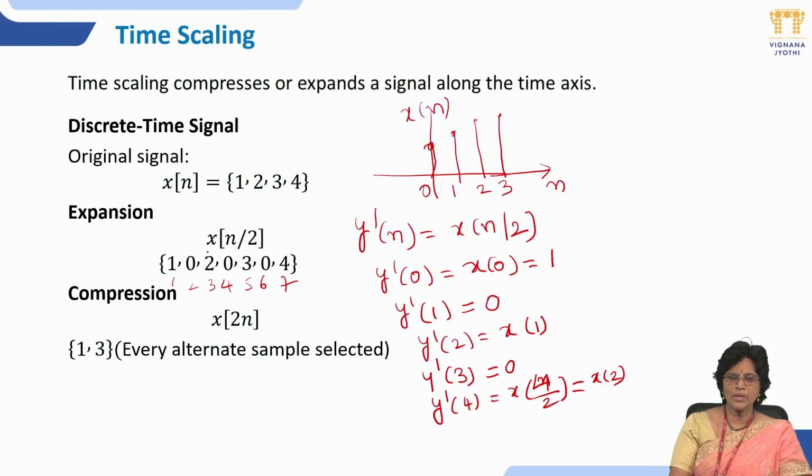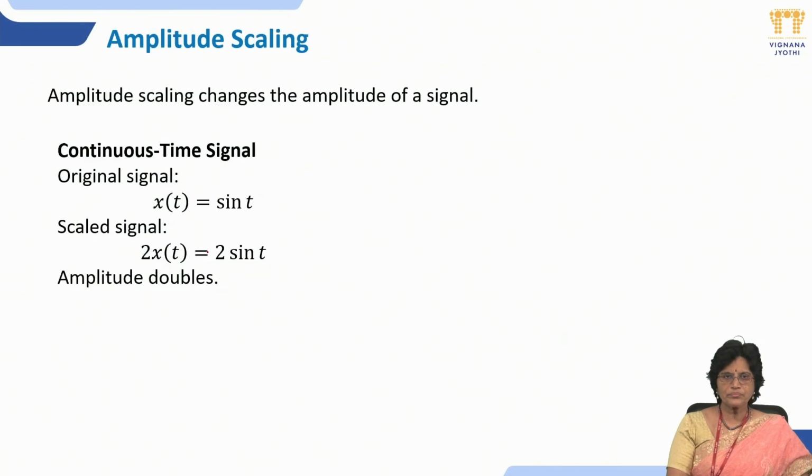In this case I am 2. So in downsampling, what we are doing is taking only one sample and discarding the sample in between. So I am keeping 1, discarding 2, keeping 3, discarding 4. Because of that, your signal, previously 0 to 3, is now coming only as 1 and 0 and 1. That process we call compression. Mainly in all communications and image processing, in upsampling and downsampling, we are using the time sampling concept.